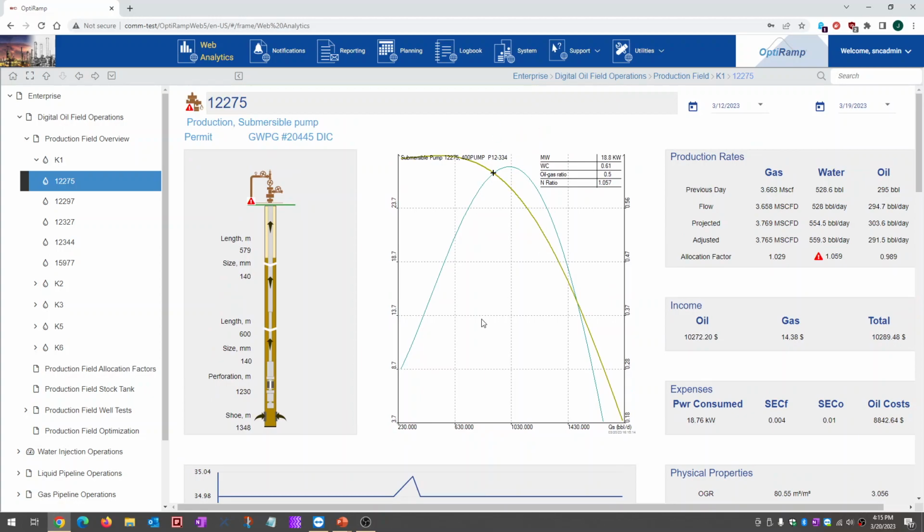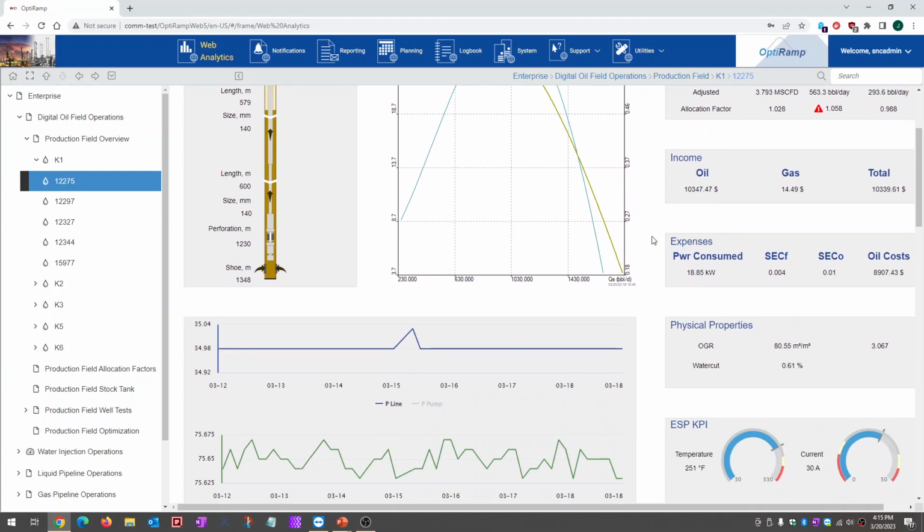And on here you can see this real-time pump curve, and you can see it start to move occasionally as data is being fed into it, and as we're constantly calculating how the well is doing and how the pump is operating. One of the notifications I see right here is we're actually getting a little too high in our allocation factor. So we just actually have a number in there where it crosses a certain threshold. So if it gets above 1.5%, then we say, okay, let's go ahead and send an alert message to that.